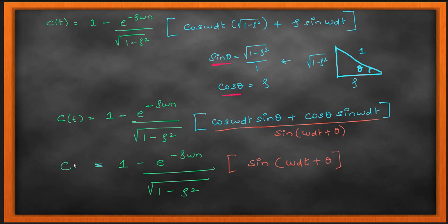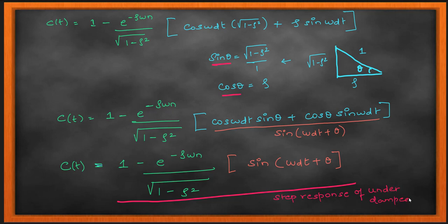So in this case, I'm going to write this as sine omega d t plus theta, and that is your simplified expression. So here what I'm having is a phase. I'm introducing omega d t plus theta, and you all know that omega d is the frequency component and theta is the phase. And now I have converted our damping into a phase term for our step response.